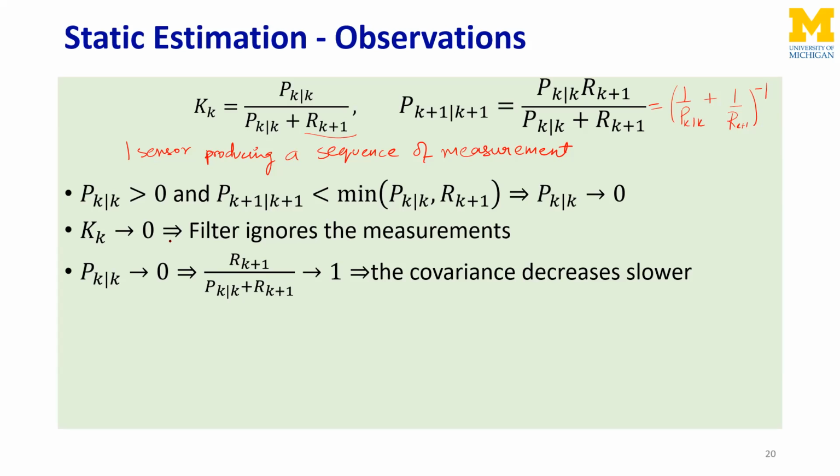The other easier solution is called covariance resetting. What you do in covariance resetting is that after every so much time, we just set PKK to be a large value, or whatever the initial value of PKK was. So after every few steps or time period, we do basically this. PKK is going to a small number, switching off, and when it goes below a threshold, P threshold, you just pull it back to the original value. So that is one way of keeping the filter alive.